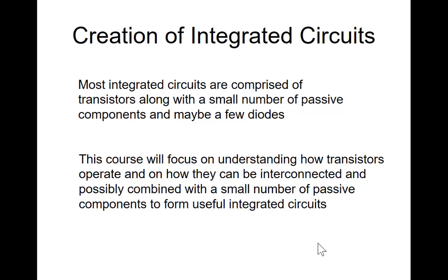This was not a production wafer. It was a wafer that was used for testing a whole bunch of different circuits. So there are op amps on here, probably data converters on here and so forth in those die locations. That's an 8-inch wafer. We'll talk about wafer size a little bit later as well. When it gets to that, could you bring it back to me? Thank you.